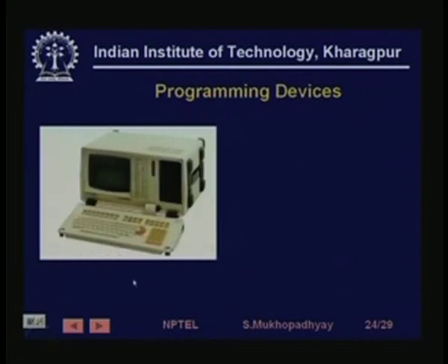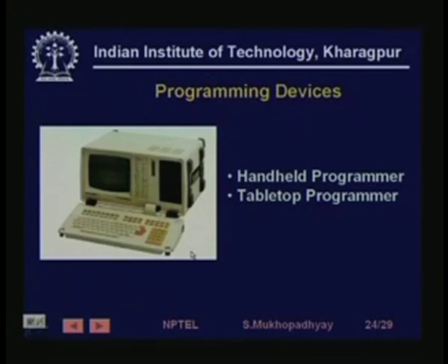Then you have to have programming devices, and this is a typical programmer. Programmers are of two types. Either they could be handheld, which you can take to the shop floor and directly program the PLC, or they could be tabletop, which are of higher capabilities, where you actually develop programs offline and then go and just load them there, because these have very good program development environments also.